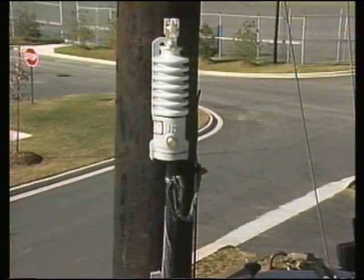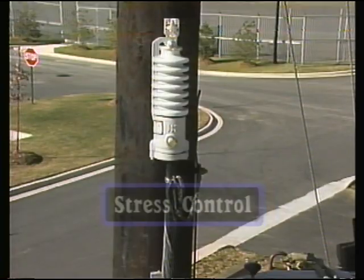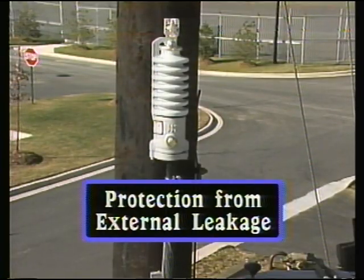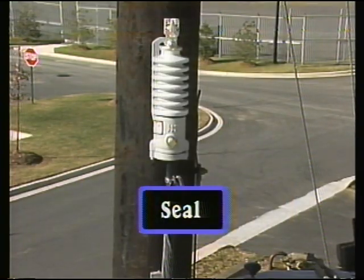A Class 1 termination provides three things. First, it provides voltage stress control for the cable's primary insulation. Secondly, it protects the primary insulation against damage from external leakage or tracking. And finally, it provides a seal for the end of the cable to protect it from the environment.